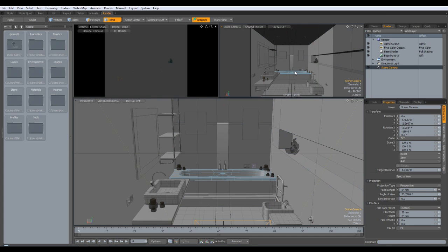Now if my head was quite high and I was looking down, or if I was a human-size figure looking up at a building from the outside, say a skyscraper, you get the effect where it goes towards a point at the top. That's correct, that's to do with the perspective. So we don't want that in architectural visualizations. We want all the verticals to be vertical.